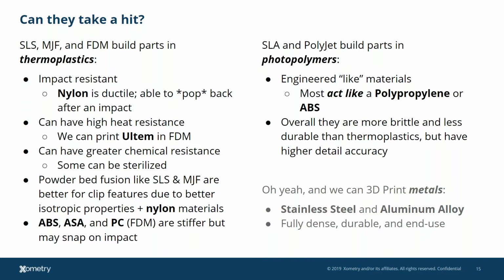In fact, I've actually moved CNC aluminum parts to polycarbonate at times to get better cost savings and just-in-time manufacturability for certain customers, because what they needed was something that remained stiff and fixtured parts together, but they also didn't want the high-end costs of CNC machining.